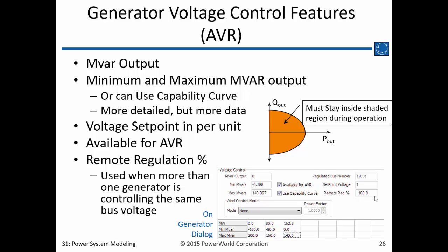It only is going to use the generators that are available. So if you have 3 defined, each supplying 1/3, however, one of them now goes offline, it will take the other 2 and say, well, one is 33.333 and the other one is 33.333. That really means they're each providing half. It does dynamically figure that out as you turn generators on and off.